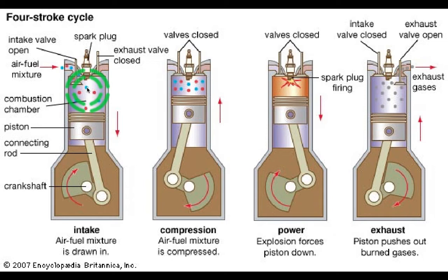This is a pump, so it's going to come down and suck in the air from the atmosphere, and at the same time injectors are going to squirt some fuel inside, so a good mixture is going to go in. How much does it squirt? Don't worry about it right now. We will deal with what an ideal fuel mixture is later on. So as it goes down, the cylinder is now filled with air-fuel mixture, right?